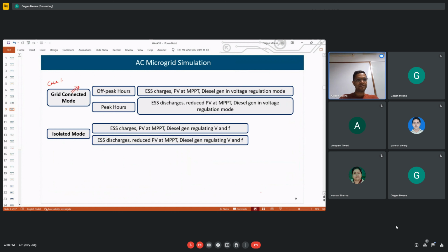Because of hysteresis. Yes, correct. The BH curve is non-linear, and because of that, especially when we start the transformer, there is the phenomenon of magnetic inrush. So there is a dominant third harmonic component in the current drawn from the supply. All these things are causes of harmonics, and they can have several impacts, like interaction with other power system equipment, motors and transformers.